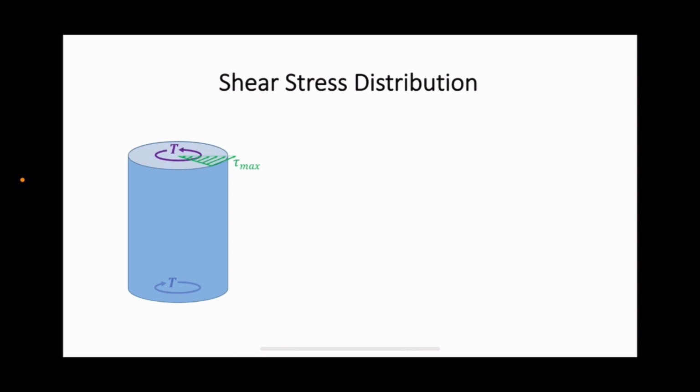To be specific, let's say this is the distribution of shear stress on the cross-section. Then if we section through the shaft further, like the following, based on the property, we will be able to understand the distribution of shear stress on the axial plane. These longitudinal shear stresses are those that cause the failure of the wooden shaft shown on the previous slide. In a similar manner, we can visualize the distribution of shear stress along another radial line of the cross-section.